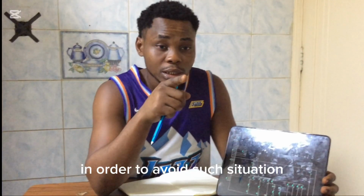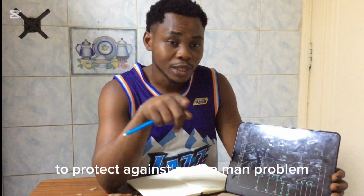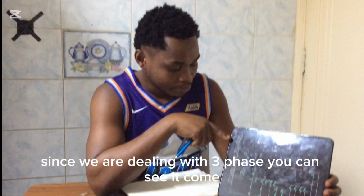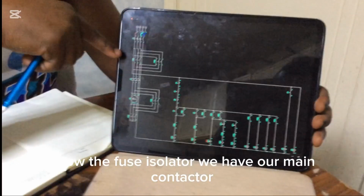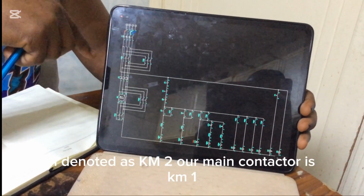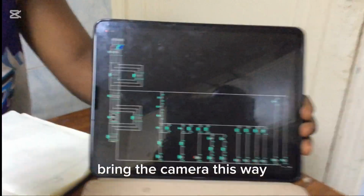In order to avoid such a situation, we always use a protective device. The protective device against such a problem is the fuse isolator. Since we are dealing with 3-phase, you can see it. Bring the camera closer. Below the fuse isolator, we have our main forward contactor, and our reverse contactor, which is denoted as KM2. Our main contactor is KM1. Now below this we have a thermal relay.